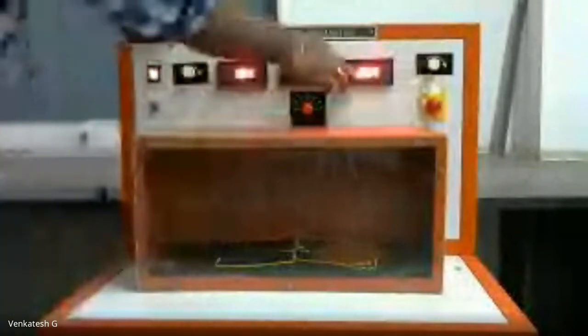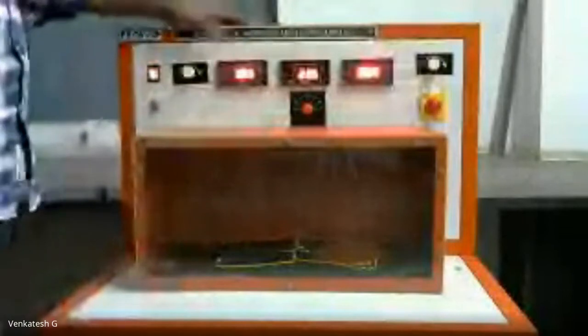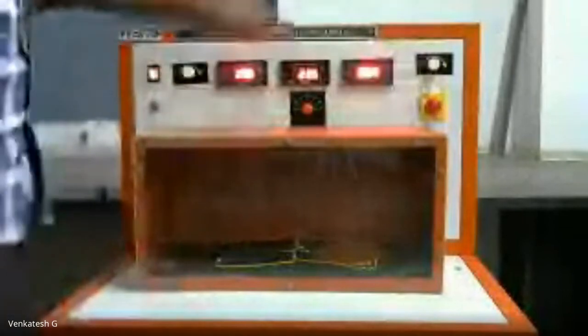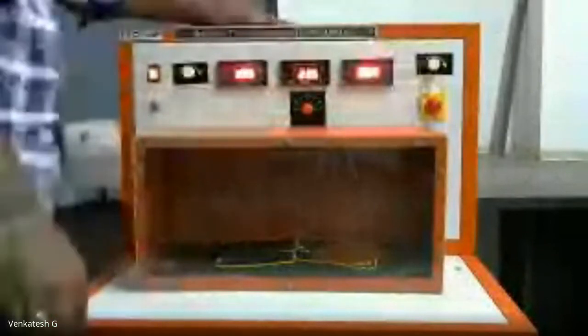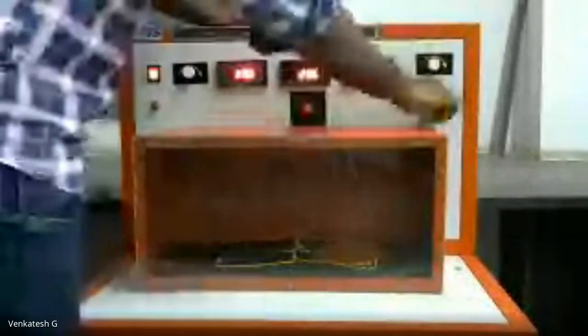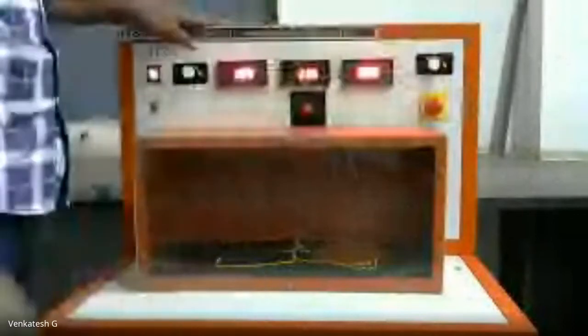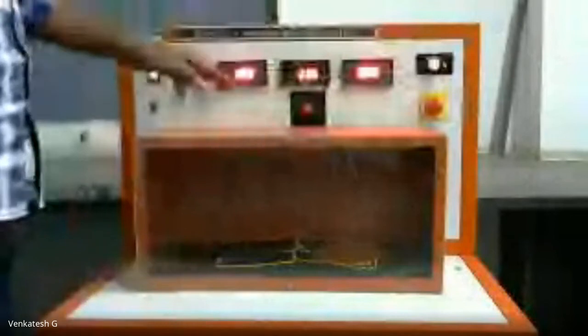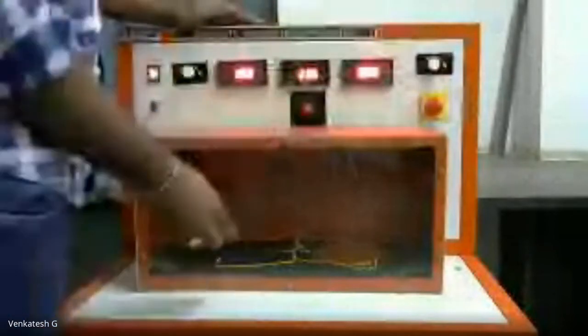Adjust the value to 120 volts, with the ammeter reading 0.53. I think this gives us around 66 watts. The same power we are going to give to the second, test plate. So now we rotate the knob to the second position and adjust it to set the same voltage and current as the first plate: the same 120 volts and 0.54 amps. Remember, we give the same power to the black plate as well as the test plate.